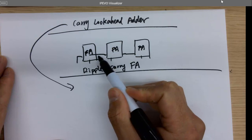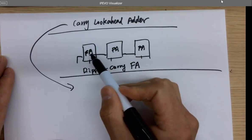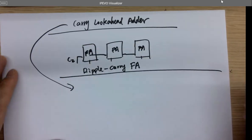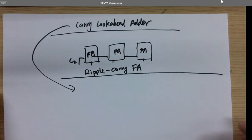The C1 is used as one of the inputs for this last stage, so it takes relatively longer to get C2 compared to other structures. However, since we know the logic, there might be an opportunity to find C2 a little bit sooner to make the adder slightly faster than the ripple carry full adder.